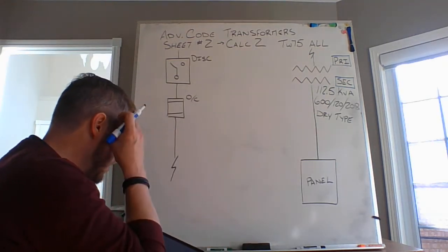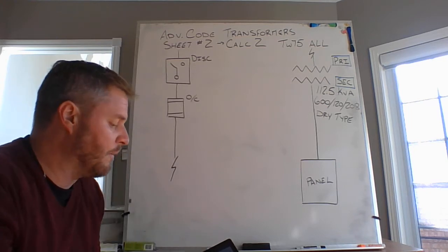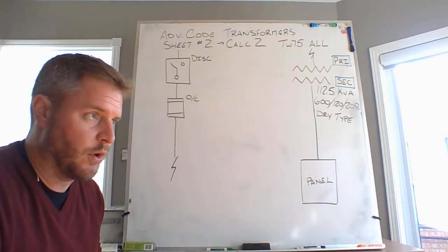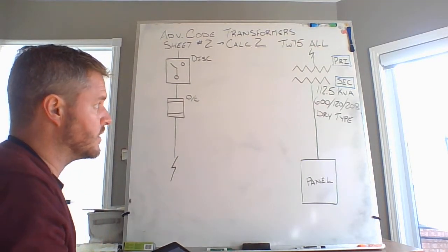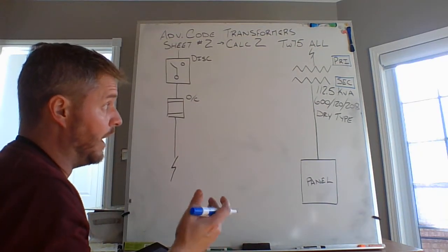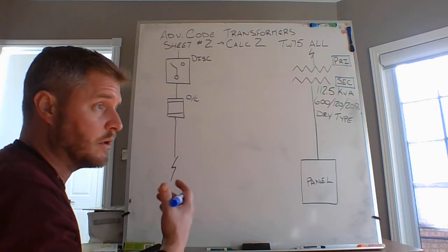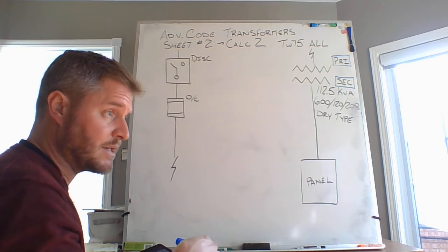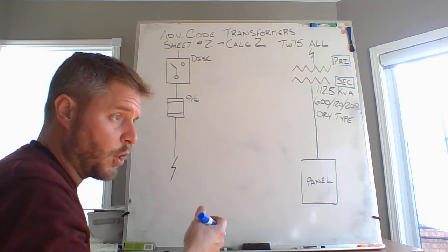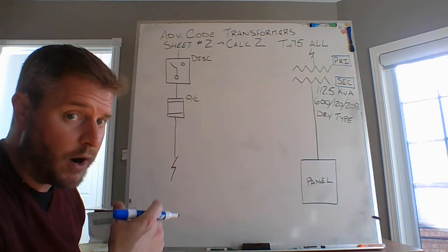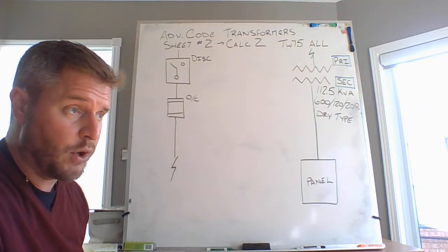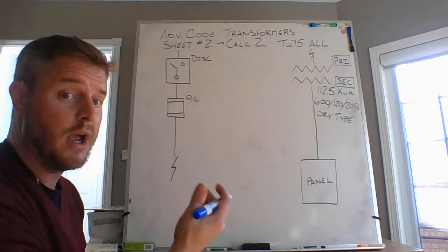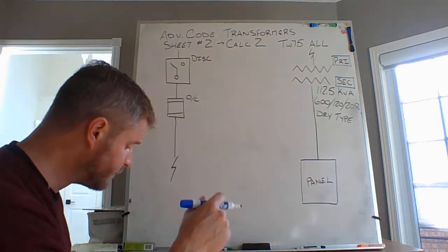So I am looking at 112.5 kVA on this specific transformer. That value is going to equal my primary current and my secondary current when I observe the fact that I'm looking for a 3-phase current value, primary and secondary, via transformer action. Now you should be far enough along in Theory A with Mr. Mankulich that you can determine primary current versus secondary current for a 3-phase transformer.